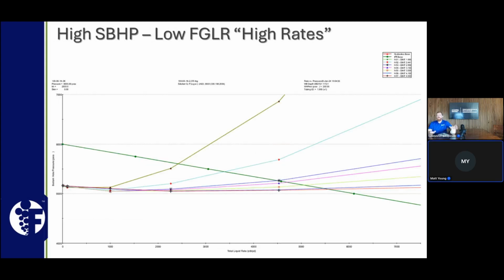And what we'll find too is as we begin to tweak some of these different configurations, we'll see that not all the time bigger is better, right? And so in this case, we have 2 of the 3 components to make a big flow path the best selection. We have decent, high reservoir pressure, and higher liquid rates. But one of the things that we're lacking in this well type is relatively high formation GLR, total GLR. So, less than 1,000 to 1 GLR.